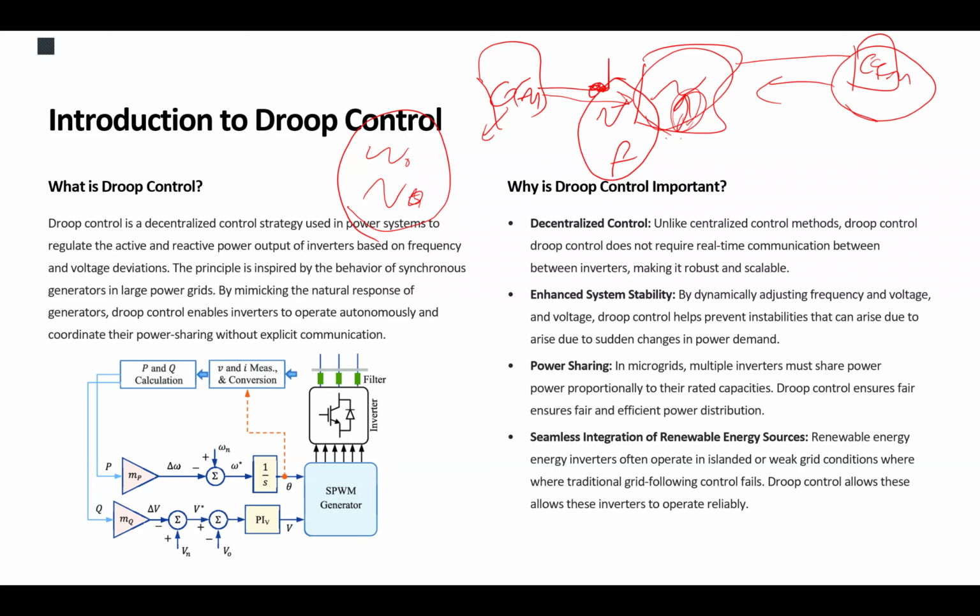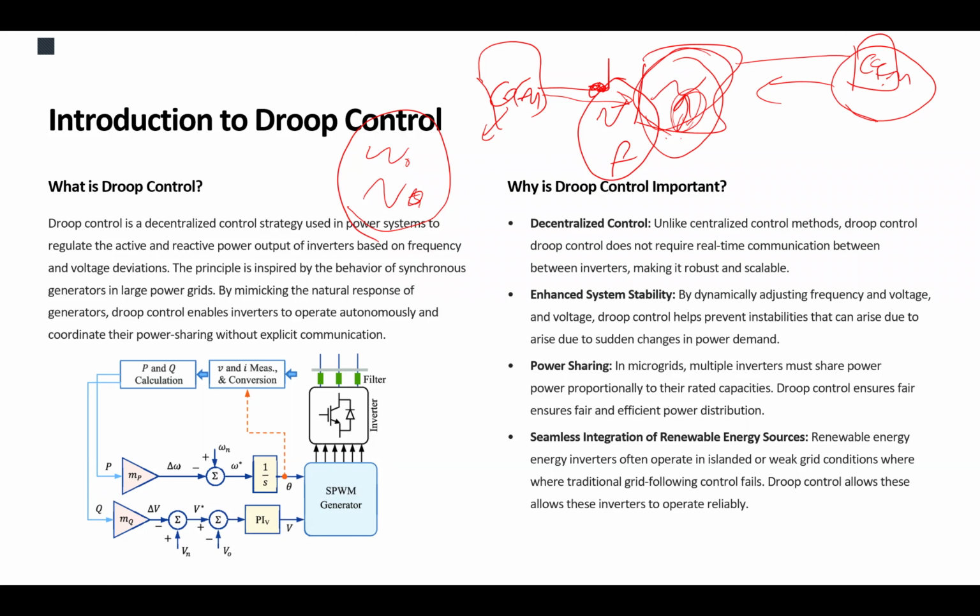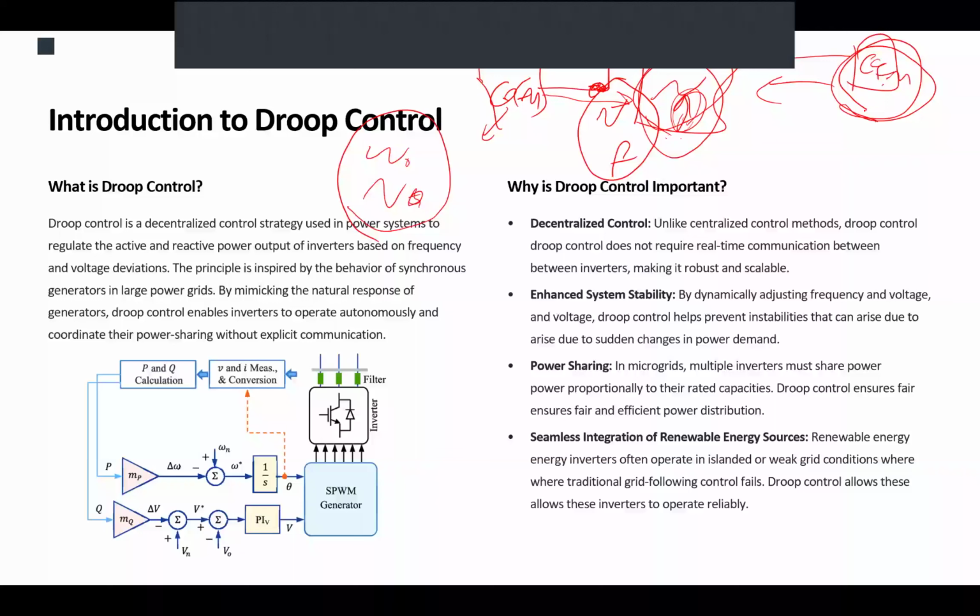So there is no communication between these two inverters in the figure. But since both of them see, for example, an increase in the load, they both try to answer that. Eventually, it means that they share the load, and how it is divided between the two is based on their own capacity. So if this inverter has higher capacity, it would answer faster to the increase of the load, and the lower capacity inverter would end up with less deviation to address. Is that clear how it works?